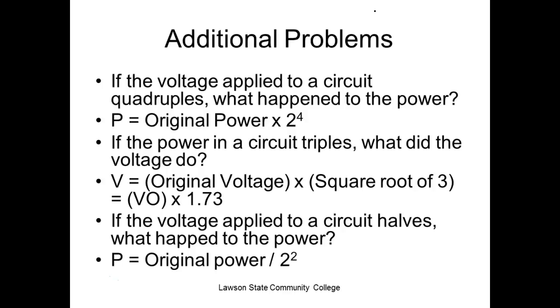Now, if I don't use circle move but use a linear move, it depends on what you want to do. If I want the arc move, then you teach a point here, a point where it levels out, and a point somewhere out here.